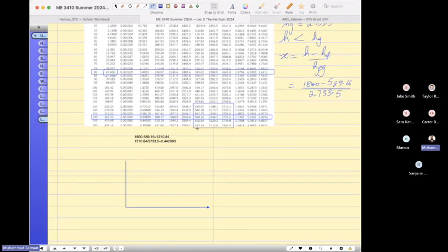So let me show you over here. This is our liquid line. This is our dry vapor line. This is our constant pressure line. Okay, guys, as you go up and up, the pressure increases. Suppose this is P2. So pressure P1 is greater than P2, and this is the critical pressure, which is very high. This is temperature, this is specific volume.